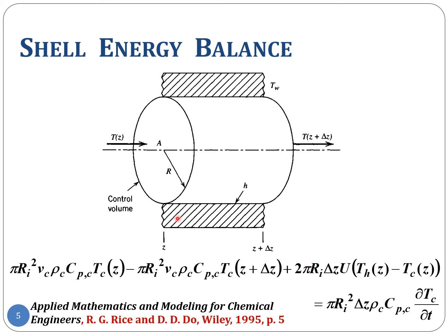So, given that this is the case, now the energy added. I want to spend just a moment discussing the energy added. This is basically U A delta T. U is the heat transfer coefficient, A is the area through which the heat is added, and delta T is the difference in temperature. That is the driving force for this heat transfer, due to what is typically called advection. So there is both conduction from the surface and conduction across the interface.